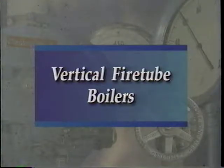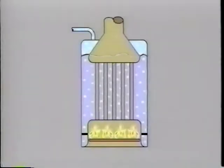Vertical fire tube boilers. Vertical fire tube boilers are one-pass boilers with the combustion chamber or firebox on the bottom of the boiler. The firebox is supported by stay bolts with a water leg formed between the inner and outer wrapper sheets. Heat is transferred from the vertical fire tubes in the water leg.